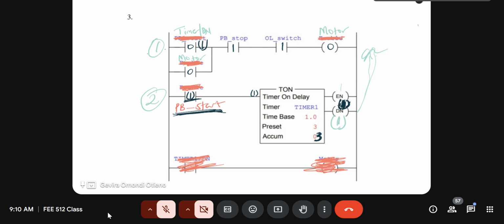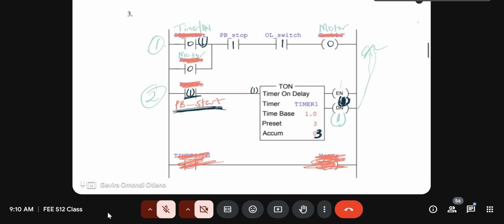So the order of the rung here isn't really going to change much for the controller, the PLC processor. Because the scan cycle dictates that you still have to read through the state of each of the components, then execute them based on the Boolean expression for each one of them. And then once you have reached the last rung, now you update the status of each contact. So it means, therefore, that it doesn't really matter the ordering of the rungs in this case. It wasn't really going to change much.